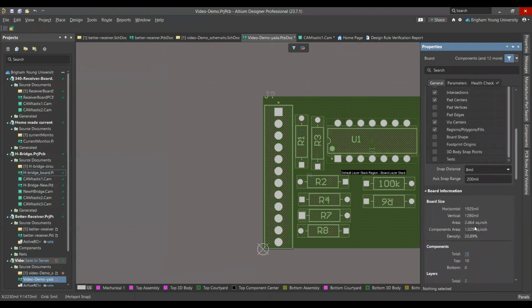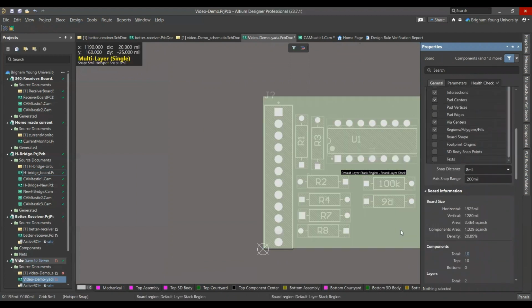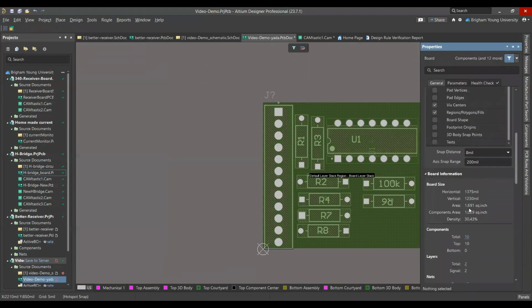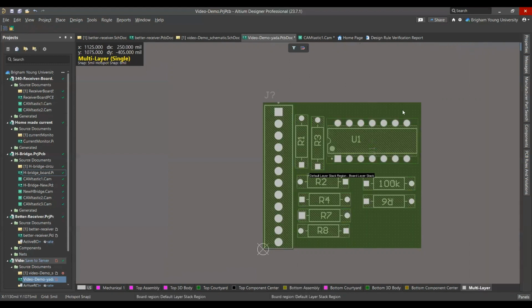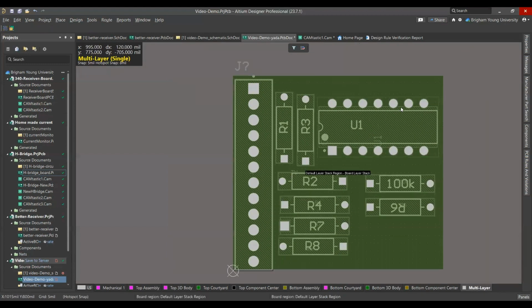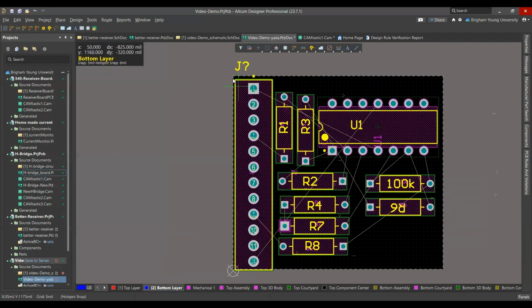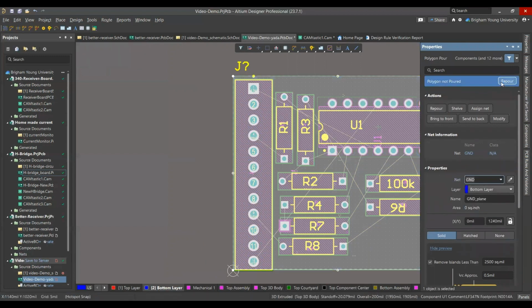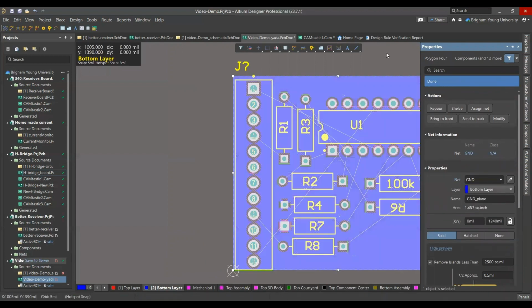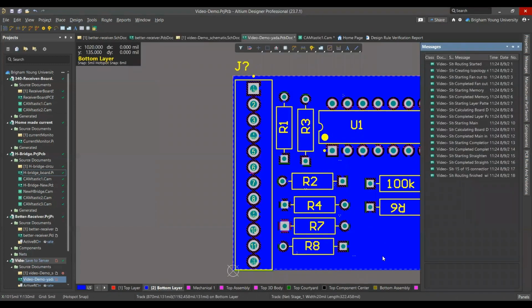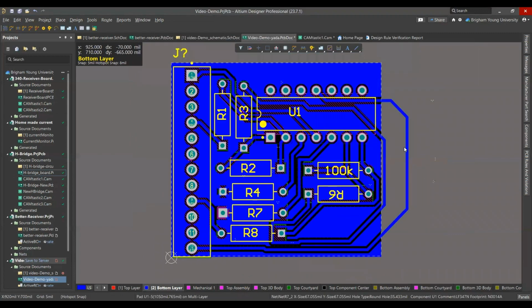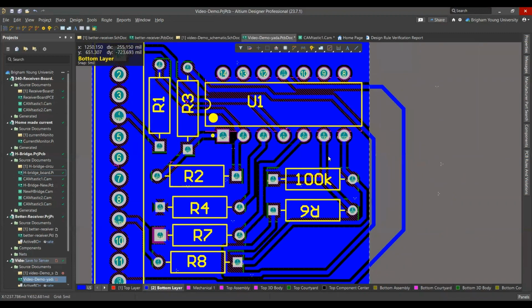Okay, so you can see that the square area is 2.5 inches right now. If I hit board shift now, and when I look at it, I'm down to 1.6, 1.7. So that's just a little bit of drilling. And then from here, you would do click 2 again, go back to here, repour your ground polygon. Make sure it's selected the right net. As you see, the auto router sometimes doesn't do everything that you want it to. Then we'll leave the board.